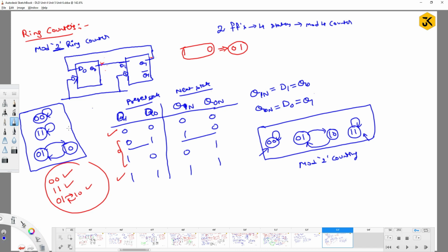So you can just think, right, guys, when we were explaining the concept of asynchronous inputs of the JK flip-flop, either active low or active high, you always produce one when the pre-state is 0 and clear equal to 1, then you are going to get the next state value as always 1.